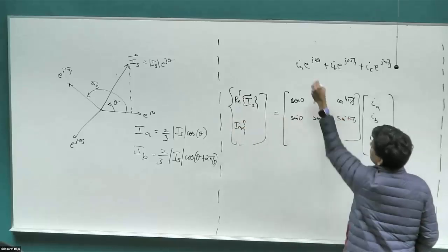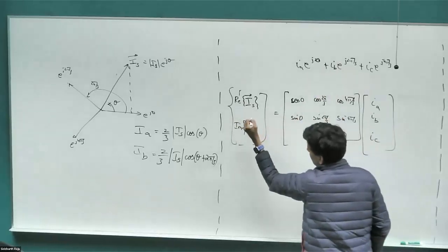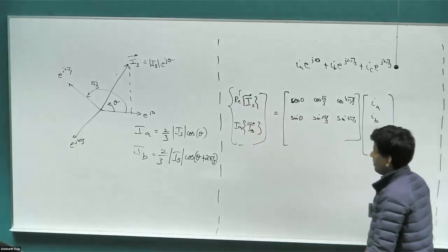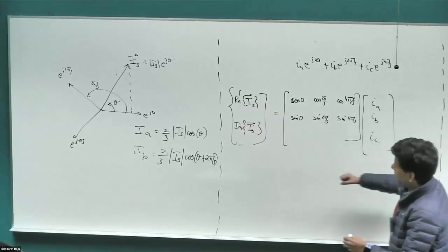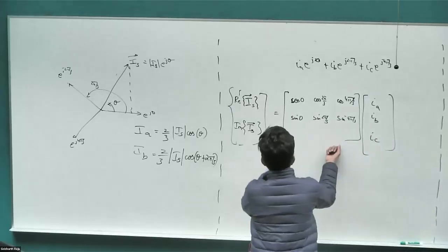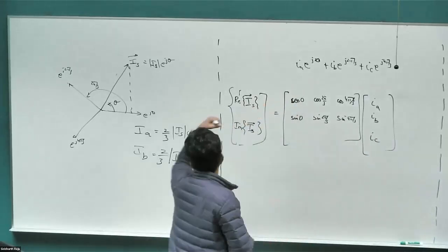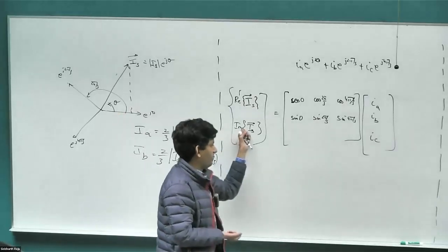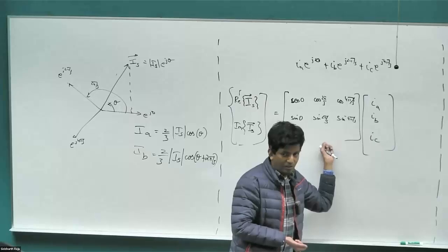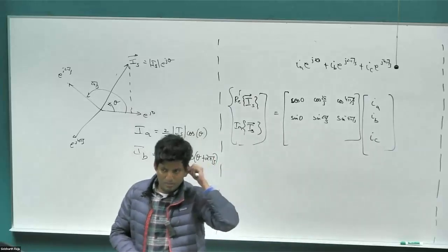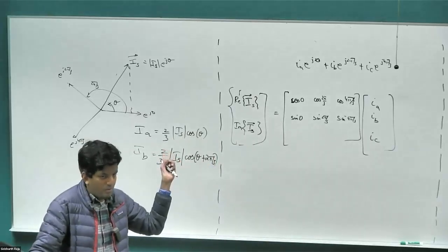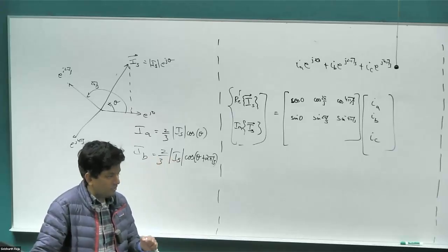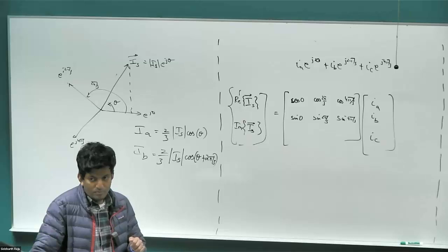Because the sine components would be the j times the value of the space vector representation. Right, so if I give you these three, you can find out these two by substituting into this matrix, which is exactly what the graphics is also doing here. But if I give you these two, how will you get back the three from the matrix? You can't invert that matrix, right? It's a rectangular matrix. But what else can I add to that matrix to be able to invert it?